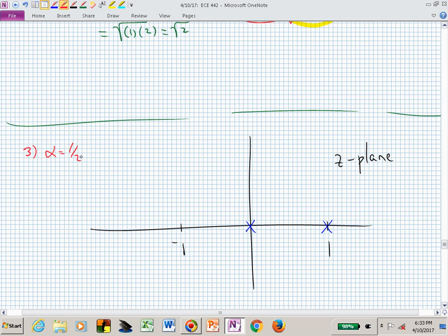What if I made alpha equal to 1/2? I'm just trying to experiment to show you that with a PI controller, I can have a lot of different possible solutions and still have the same steady state accuracy. In each of these cases, as long as I stay stable, my steady state accuracy will be 0 due to a constant input. My transient may be different.